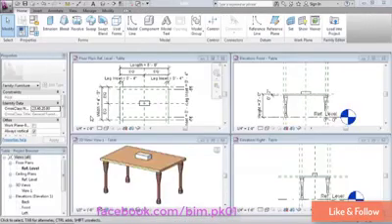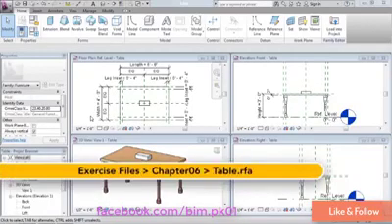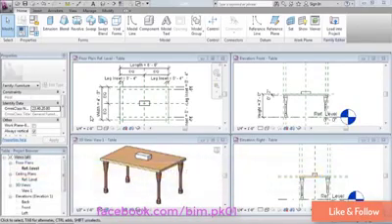In an earlier chapter, we explored the 5 geometric forms that we can create in the Family Editor. All 5 forms use at least one sketch to determine their shape. 2 of those forms, however, the sweep and the swept blend, offer an alternative to drawing the sketch directly in the form. They can instead use a nested profile family. A profile family is just a 2-dimensional closed shape.